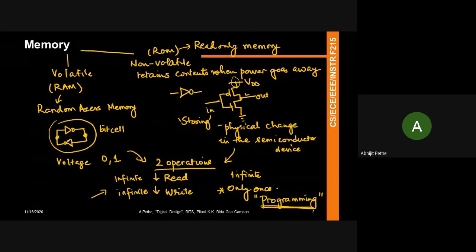You need to use it once, and you don't need to change it every now and then. So it's a ROM which is programmed once, and then it is accessed every time you turn on the computer, and that sets up the first few instructions of the computer to reset everything, to give your startup program, and then you go into the regular operation. When you start using the computer for computation, then you begin to use the random access memory because you need fast access to data.